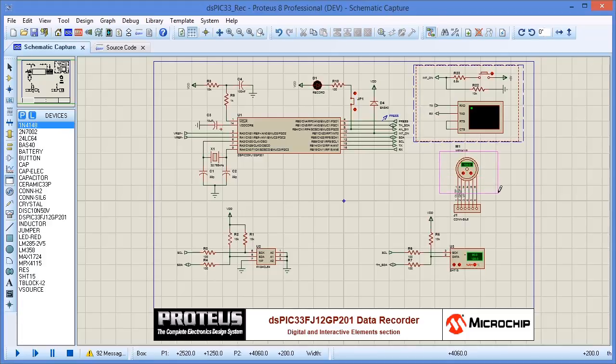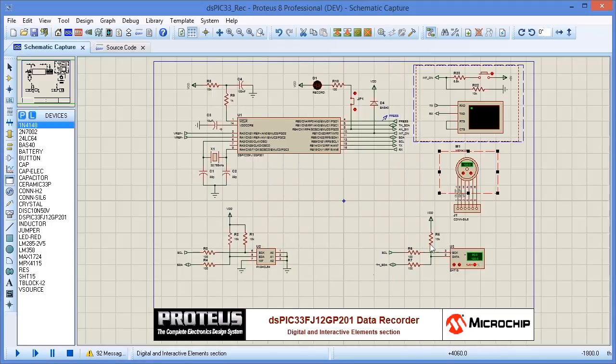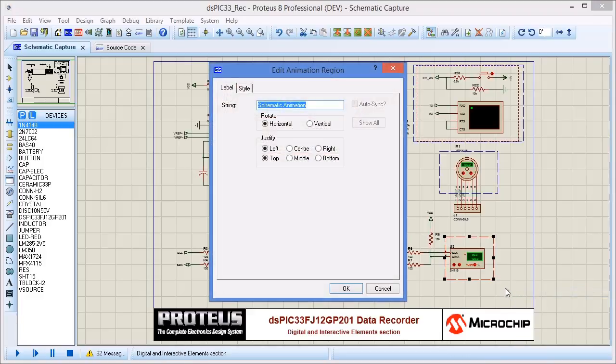when debugging. Select Active Pop-up mode from the left-hand menu and draw a box around a single area of interest. Right-click on the drawn box, edit properties and enter a name for the pop-up. This can be repeated as many times as you like for the simulation.